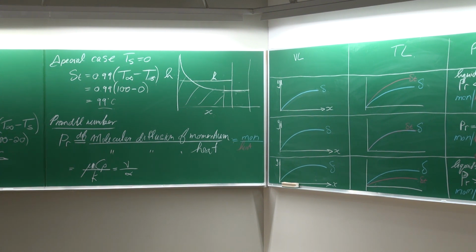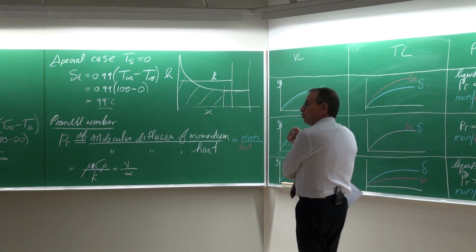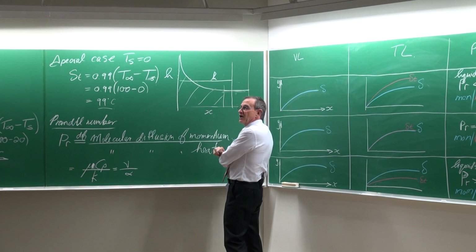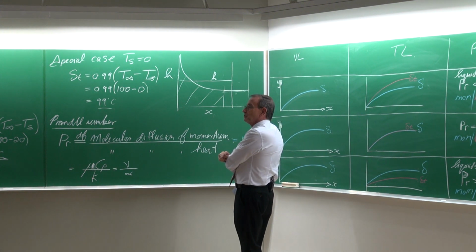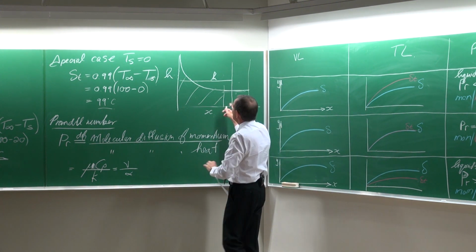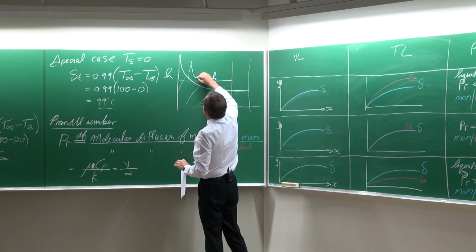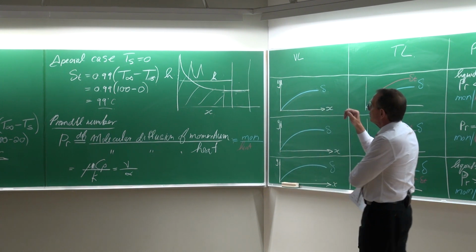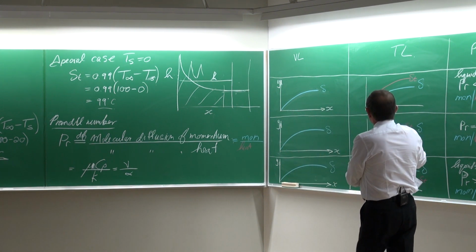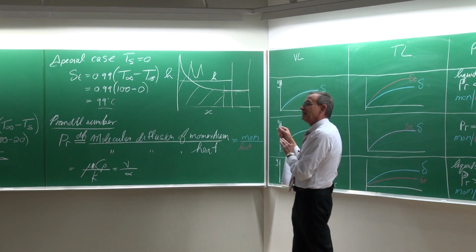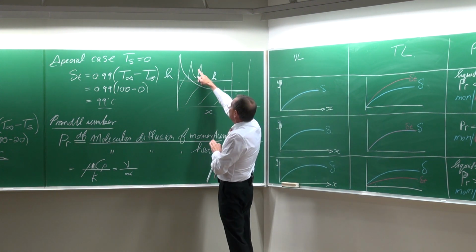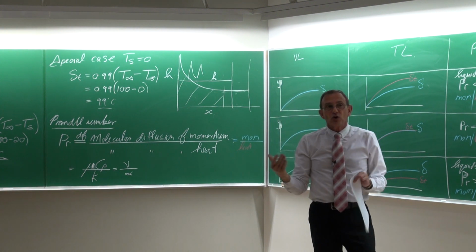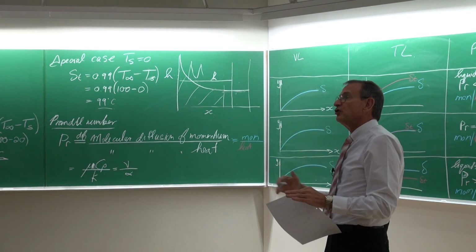Okay. It is also important to understand that this boundary layer can actually be disturbed, because by putting in disturbances, you can keep on changing this boundary layer. You can change the boundary layer to start growing again every time. And when you do that, the heat transfer coefficients will increase significantly, and that is part of heat transfer which is known as enhanced heat transfer.